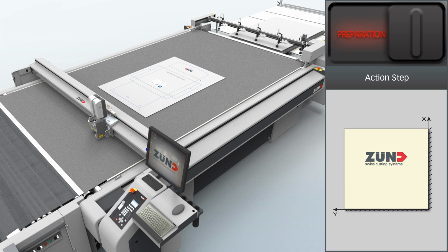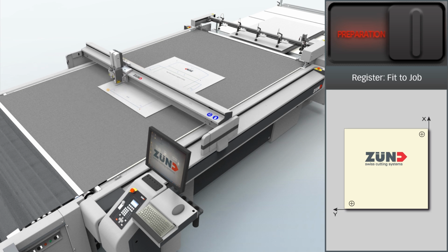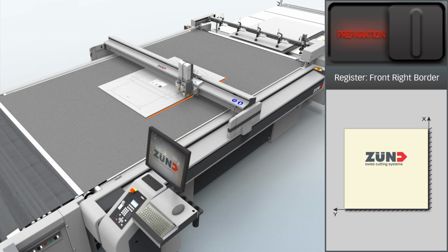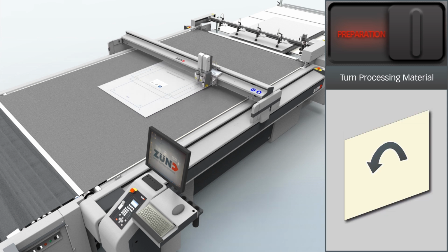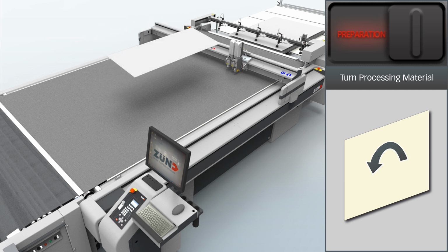The first panel is fed in with the printed side facing upwards. We start with the registration. With this production step, possible distortions are detected. You only have to do that once. The values are saved for the whole production. Now register the material borders. This is necessary because later we want to process the material with the printed side facing downwards. Turn the panel. This action automatically flips the cutting path.